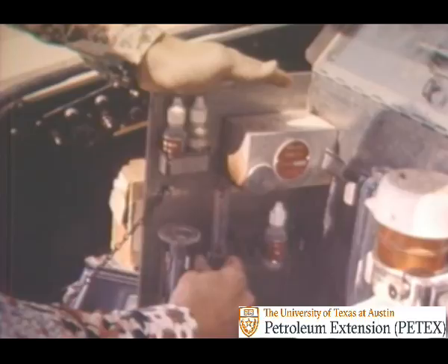This is a mud still or distillation unit. It is used to determine the percent by volume of solids, water, and oil in the mud. It evaporates the liquid part of the mud, leaving behind a residue of solids. All muds operate at an optimum solids concentration for a particular mud weight. For this reason, determination of the amount of solids is one of the most important checks a mud engineer makes.